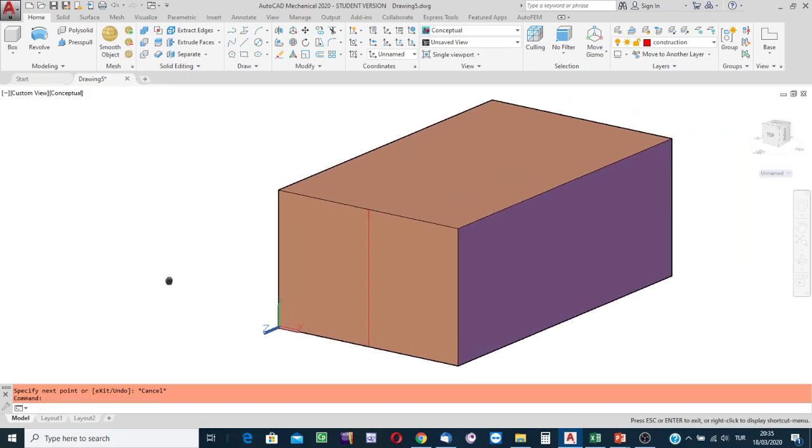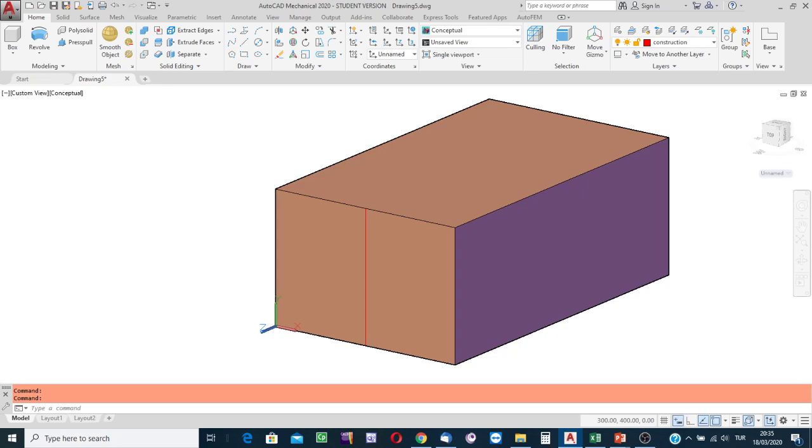Where is the profile? The cross section of the ring. My purpose right now is to create a ring as a revolved feature, and the profile is circular. Since it is circular, start the circle creation process. From this list, I'm going to select the diameter option.